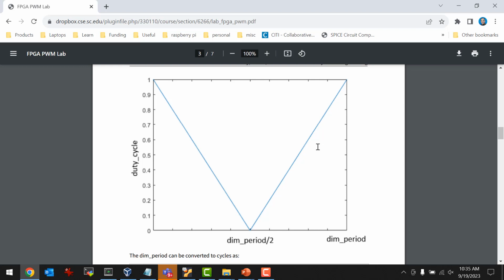It's essentially a conversion process. You're going to be continuously reading the performance counter and then doing some calculations, basically using a modulo operation, to convert that counter into a PWM and this dimming pattern, the breathing effect, the off and on thing. Does that make sense?